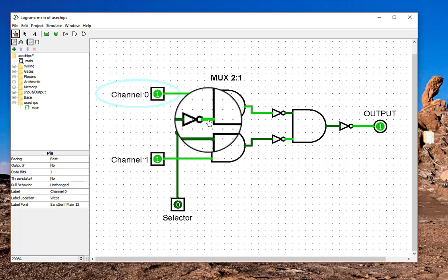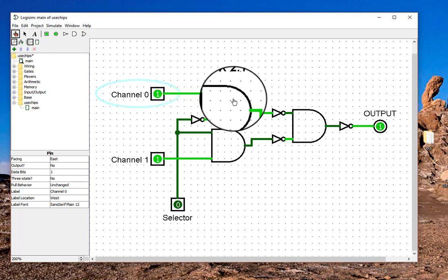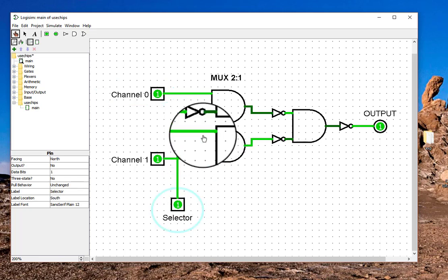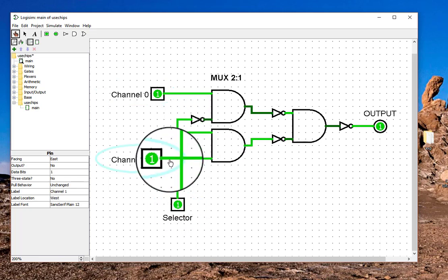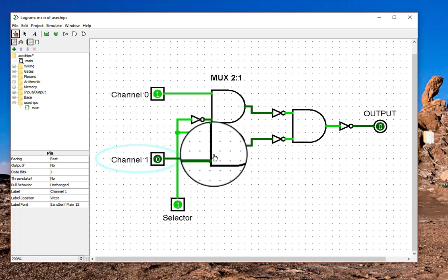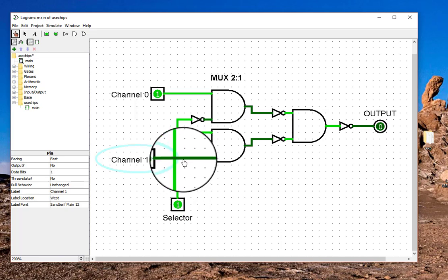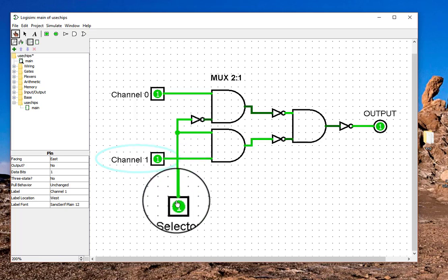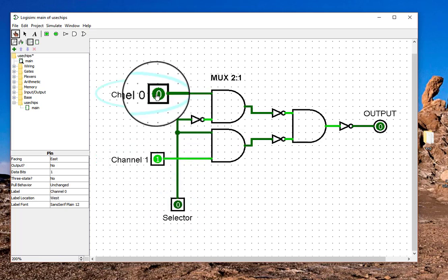It's like multiplication. This is 1 times x is x. Down here it's the same thing. This is like 1 times x. Channel 0 is x, and channel 1 is x. X is x. So no matter what happens, channel 1 is x, and it just effectively is a copy of x. When I go to 0, whatever's up here, it's coming out.